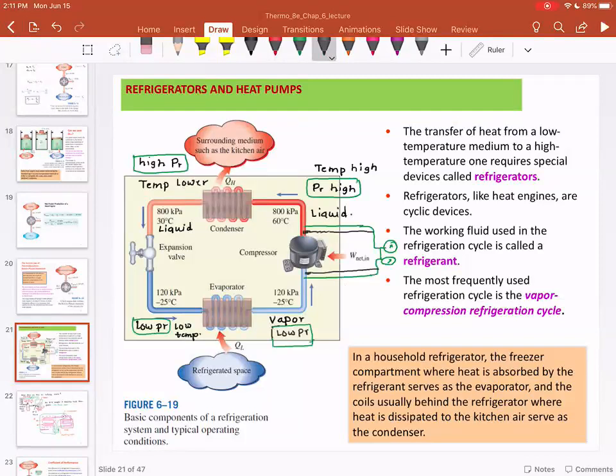If there is an impurity or an obstacle, which is very common with old air conditioning systems, or if you have a clogged expansion valve, the high side pressure is very high and low side pressure is very low because the refrigerant is not flowing. In that case, the compressor heats up, there is a thermal switch and the compressor gets turned off.